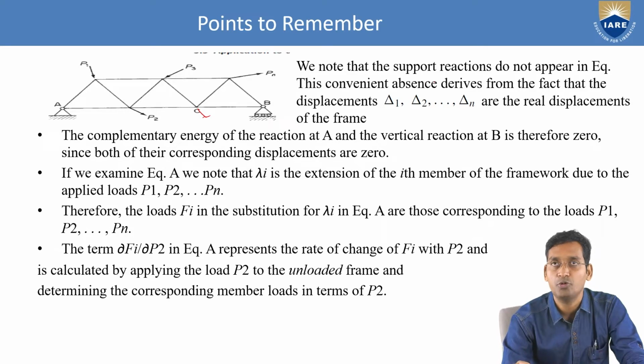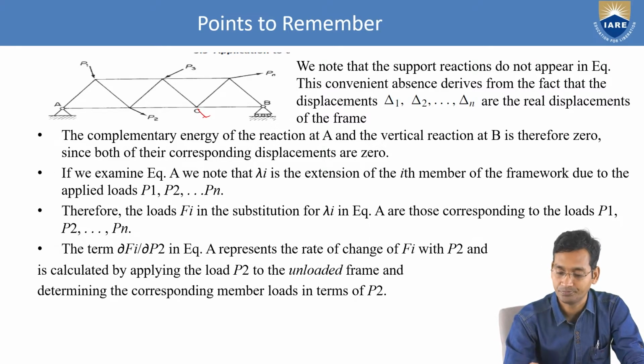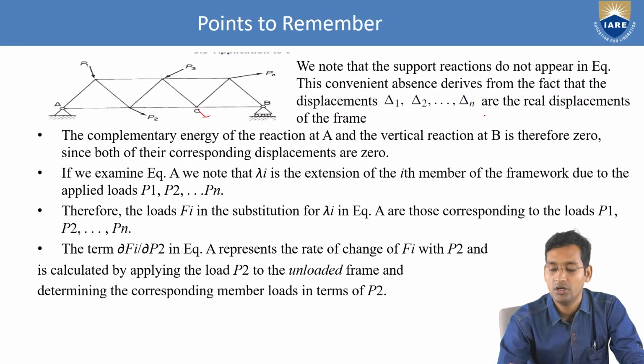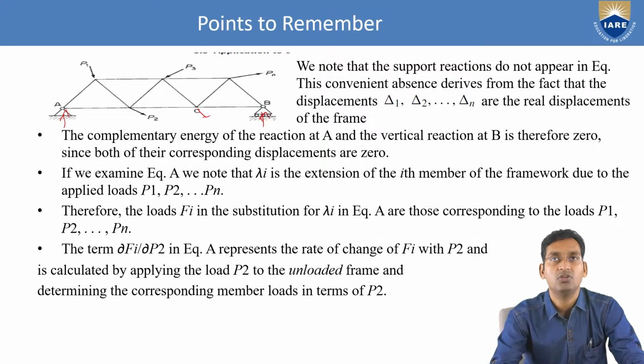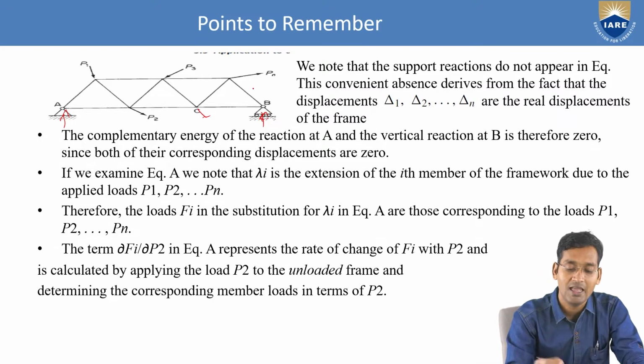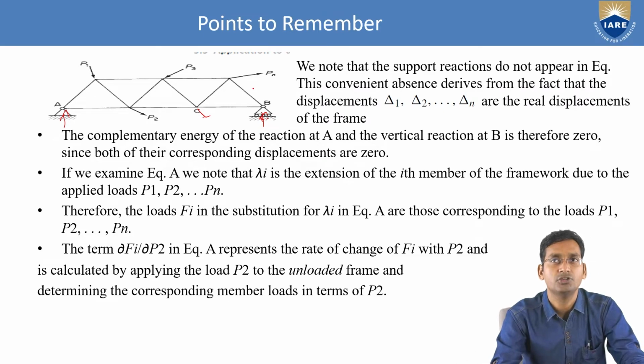So we know that the support reaction does not appear in the equation. Have you seen anywhere that a support reaction is there? No, there is no support reaction, only the load acting or the virtual forces we are considering. This convenient absence derives from the fact that the displacements delta 1, delta 2, delta 3, and so on up to delta n are the real displacements of the frame. Means there is no reaction in that equation, so the reaction value is not required. How much reaction the simple support will provide on the surface, there is no need to consider.